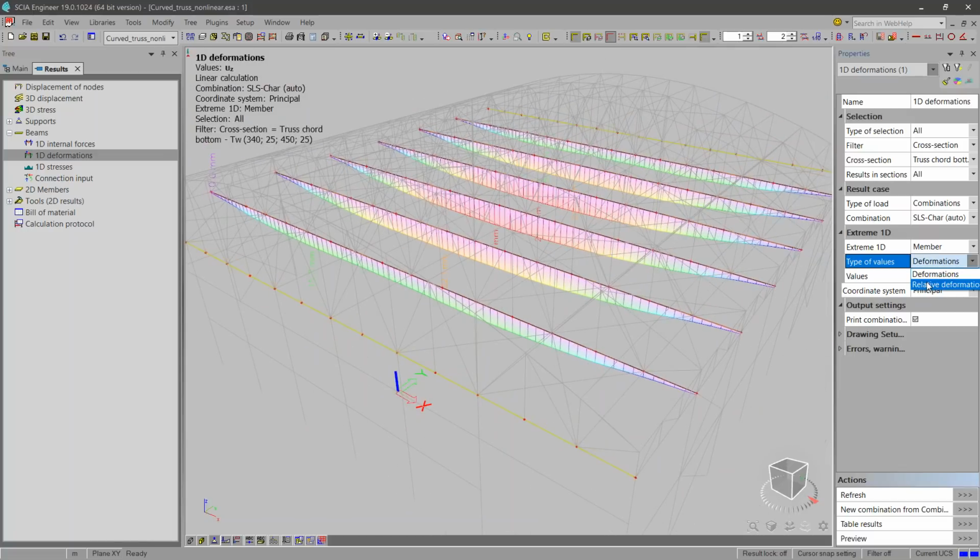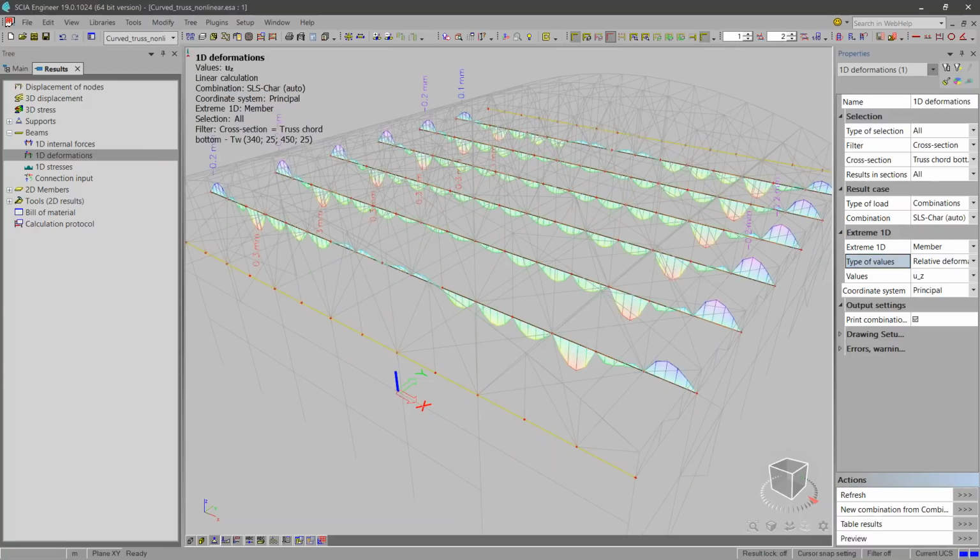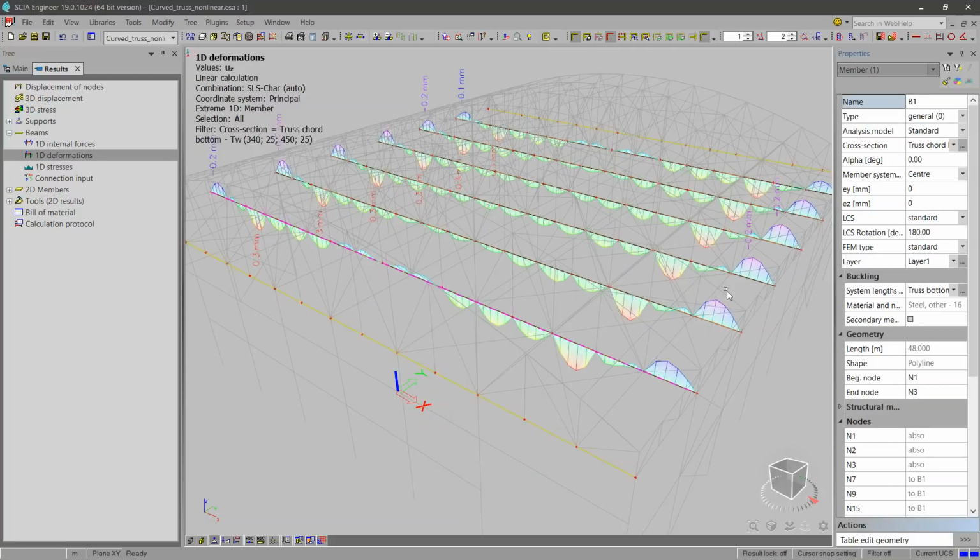The relative deflections are also available in the service results. But what is the difference here? Let me just right now click on update, and what I will see is that the relative deflections are not what I expect. I will show you the reason why. This is, let's call it, an existing functionality that it's important to understand before we run the SLS checks.